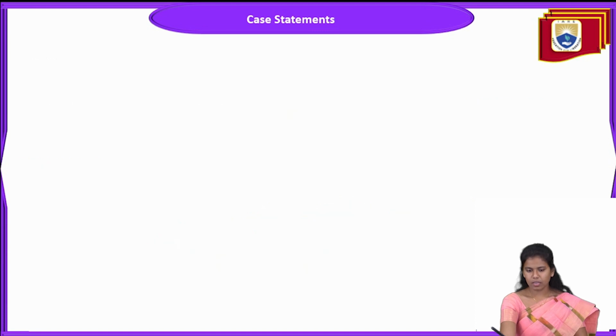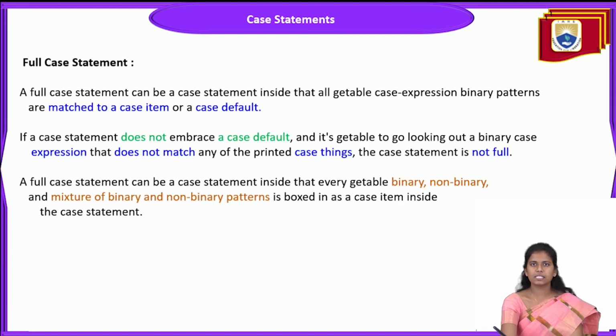Okay, and the full case statement. What does this term full case statement mean? A full case statement is a statement where all case expression binary patterns are matched to a case item or case default.